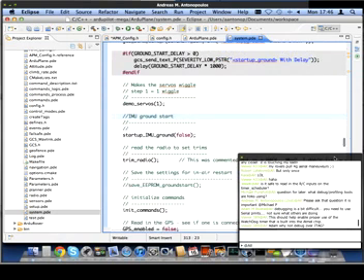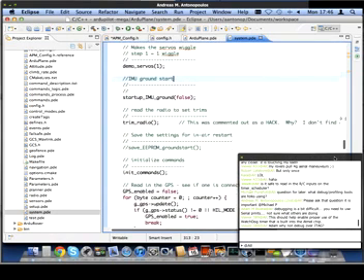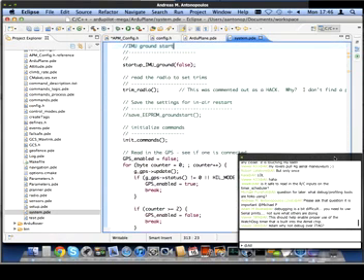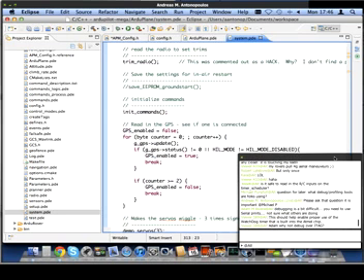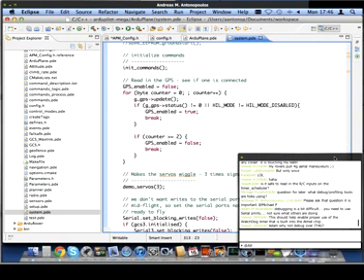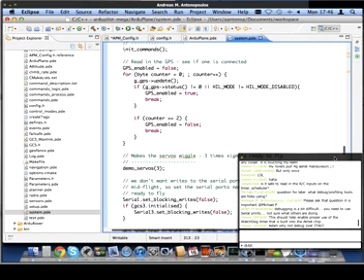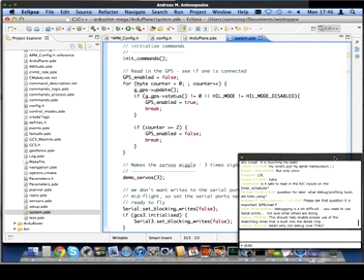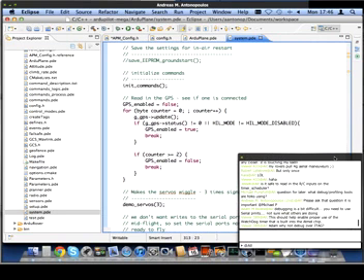It also gets things like the 0 point on the airspeed indicator, the expected value when you're not moving, which is why it's quite important, if you've got an airspeed indicator, that when you're starting up ArduPlane you put your hand to loosely cover the pitot tube so that you're not getting wind, if it's a windy day, flying past your pitot tube and giving it a bad offset.